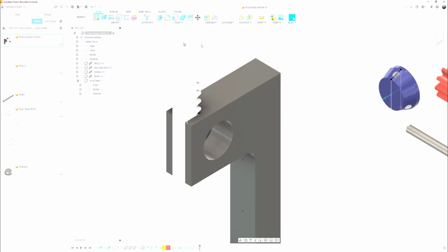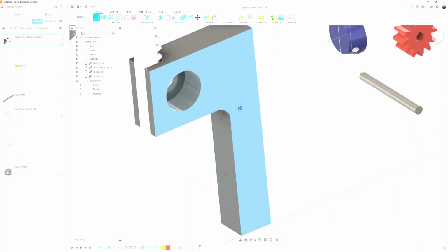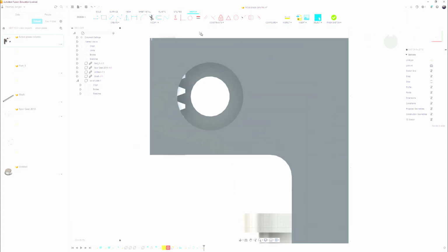activate the column. Well, why do we want to activate the column? Well, we want to activate the column because the column needs to have holes drilled on this side to meet that mounting plate. So the same thing is going to happen with this column, is that we're going to have to lay out a sketch, put a point on, and then create the multiple hole positions for that object. So we'll put a sketch, since this is our current object right now is the column. I'm going to go ahead and put a sketch on the side of the column. Because ultimately we're editing this column now.